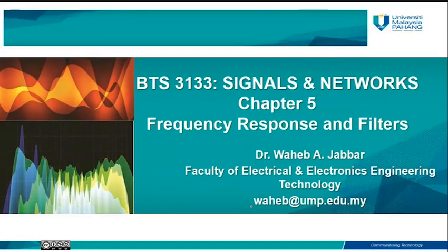Based on the components of that system, the relation between the output and input will change, and the transfer function is used to calculate that relation. If we have some given information about the input of the system, like an input voltage source or input current source, we can calculate the output of that system in the frequency domain, not in the time domain like we learned before in circuit analysis.